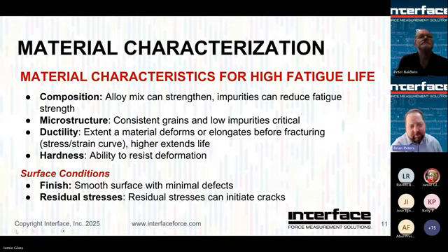Surface conditions, pay attention to that. We want smooth surfaces on all of our load fixtures, everything in the assembly. Again, it all starts with cracks. Also pay attention to any residual stresses, depending on how that material was tempered or finished.